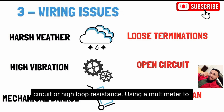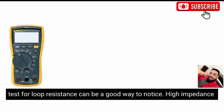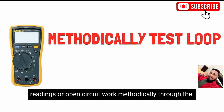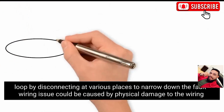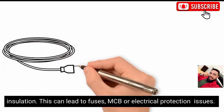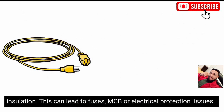This could also be a voltage drop or high loop resistance. Using a multimeter, you can test for loop resistance, and it's also a good way to notice this fault. Open circuit the loop by disconnecting at various places to narrow down the fault. A wiring issue could be caused by physical damage to the wiring. This can lead to fuses, MCB, or electrical protection issues.